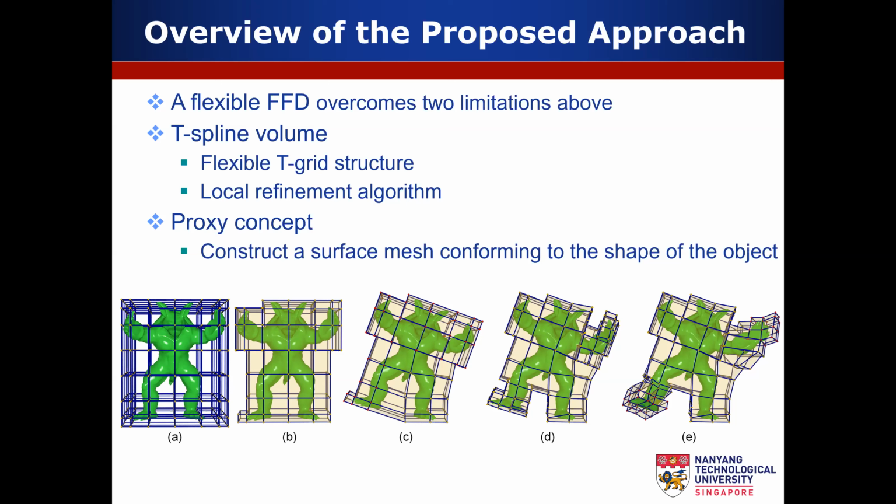Secondly, T-spline has a local refinement algorithm, which could change the topology without changing the shape. This property makes the topology of the lattice and proxy changeable. Previous work which applied T-spline to FFD only used the first property, not the second. We make full use of the advantages of T-spline to overcome the fixed topology limitation, so that the topology of the control lattice can be changed during the deformation process.